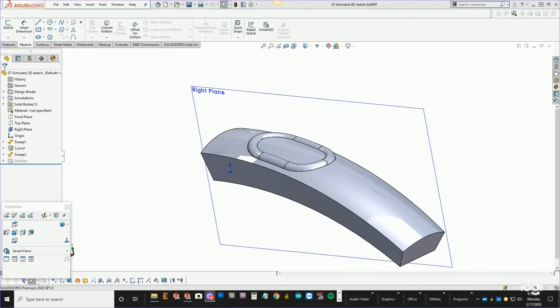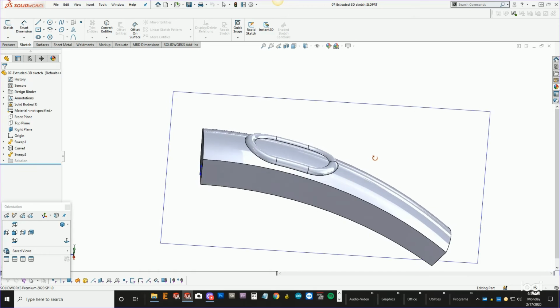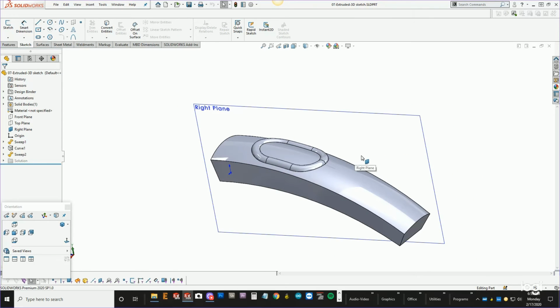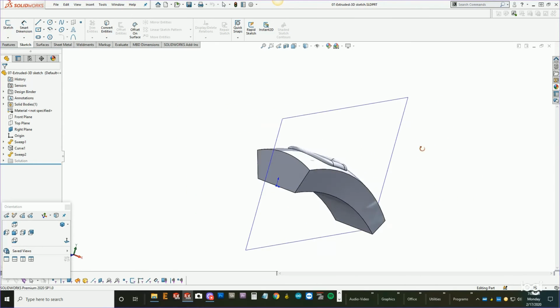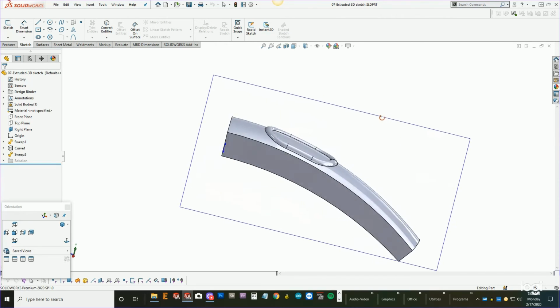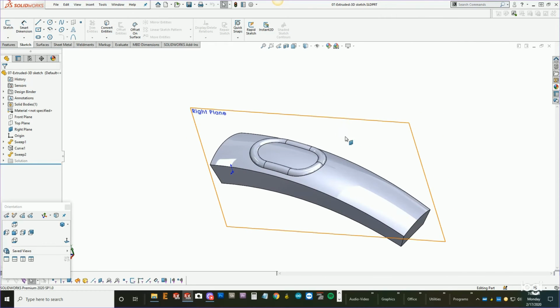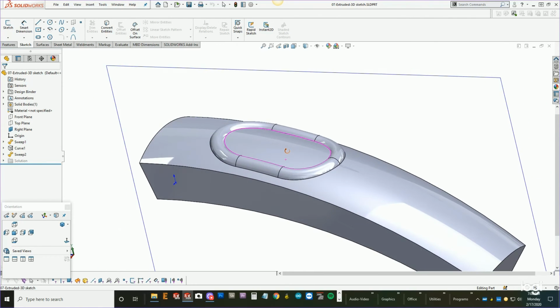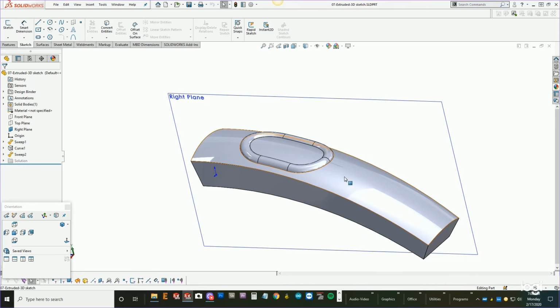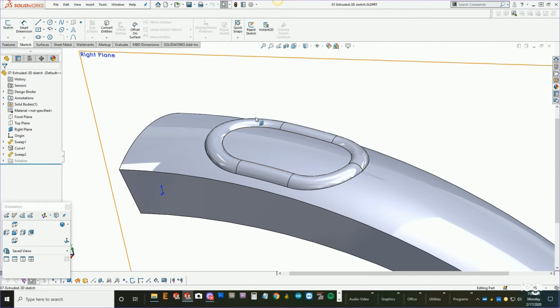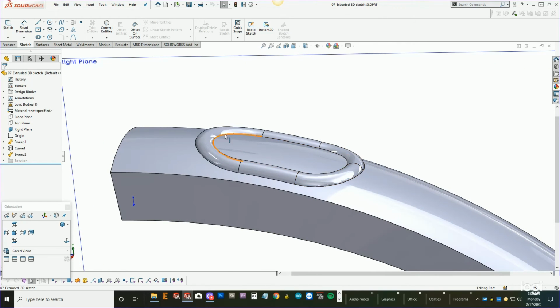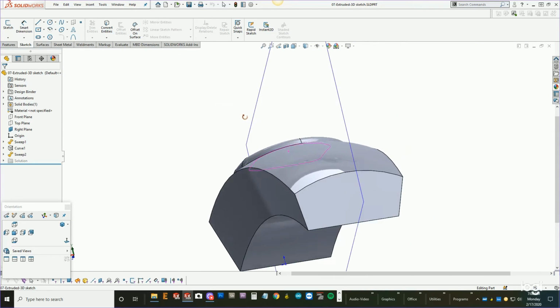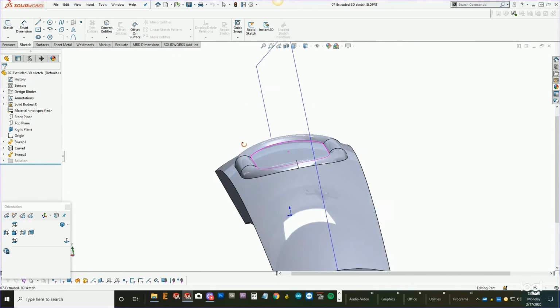In this next example, did you know that you can extrude or cut a 3D sketch? In some cases that becomes useful when you don't have a planar reference. Like for instance, at the start of this controller handle, I have an interface area. I need to cut a pocket in here normal to this existing face. And so I'm going to use 3D Sketch to cut into that.